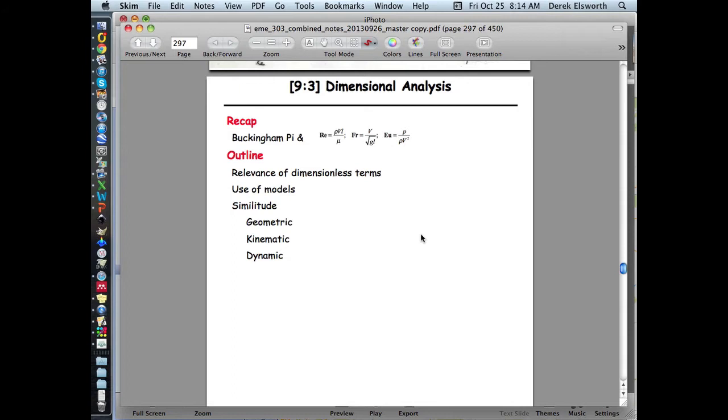And so you'd have gathered, I think, from that material that dimensional analysis, which is kind of a misnomer really, because you're trying to make them into non-dimensional numbers, is an incredibly powerful tool that allows you to say something about the behavior of fluid mechanics systems without ever really writing an equation or deriving a differential equation. It allows you to do experiments, and by judiciously choosing those experiments to scale those up in some way.